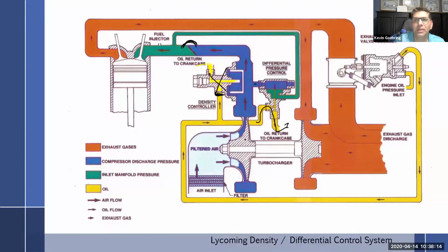So I can take this system and honestly, all I can do with any other system is just add different controllers, which are nothing more than different personalities trying to do something different. But for the most part, this is it. This is everything. You just add different controllers that are sensing something else or doing it in a different way. But every single controller from here on out, every single system that uses oil does exactly this. Supplies engine oil pressure.